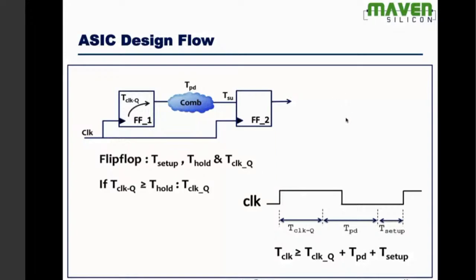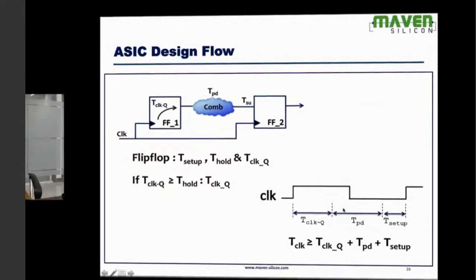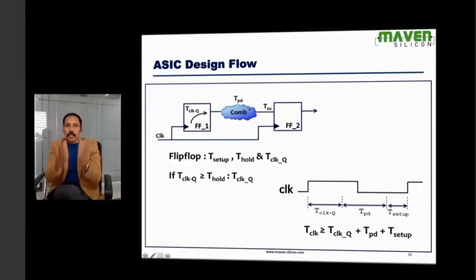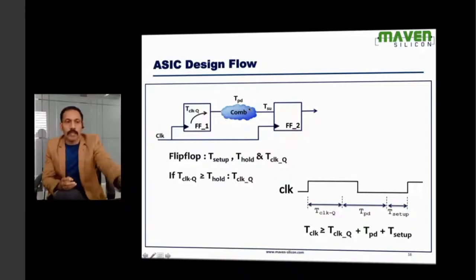Now, when it comes to design, basically, we look at whether we can do everything comfortably within this clock period. You have created the architecture, you have written the code, but during synthesis, you might come to know that the propagation delay is more. That's where you have to apply optimization technique. You have to minimize the logic. That's why you always go for K-map techniques. This is something about RTL. Now let's look at the coding.